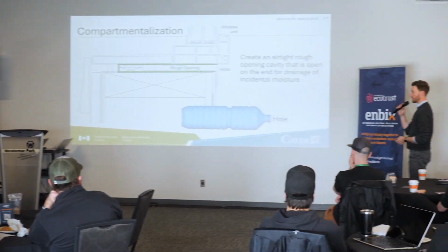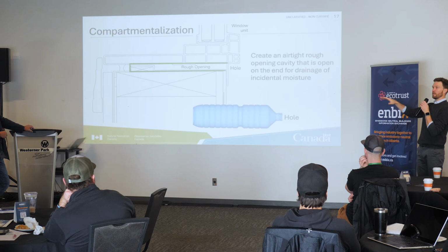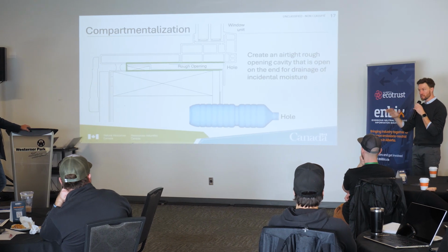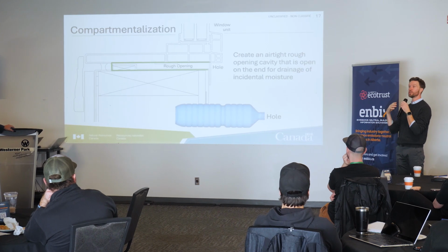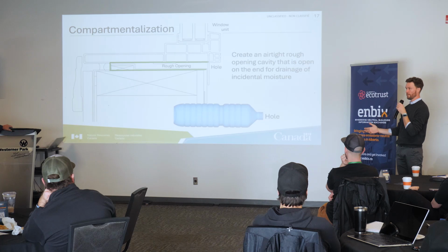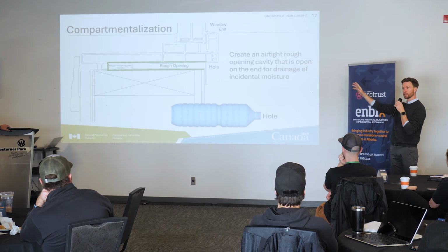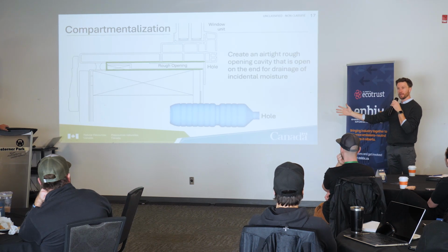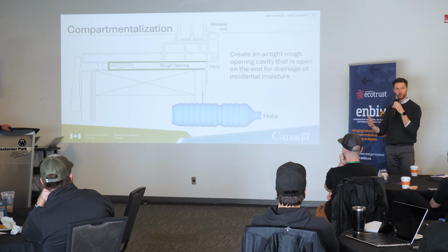Because it's so near and dear to my heart, I got to jump in because I love this slide for this example. I can't stress enough that in all situations, air leakage through our assemblies introduces more water than it carries away. So all of the drying and draining that we're talking about here is not contingent on air moving from the inside to the outside to dry out an assembly. That will always hurt your assembly more than it helps it.